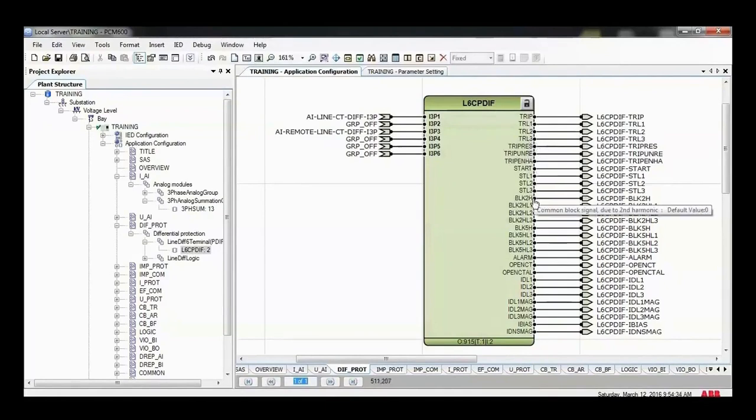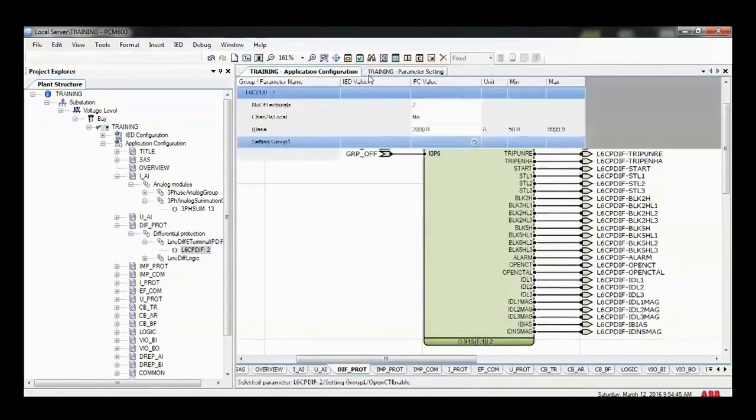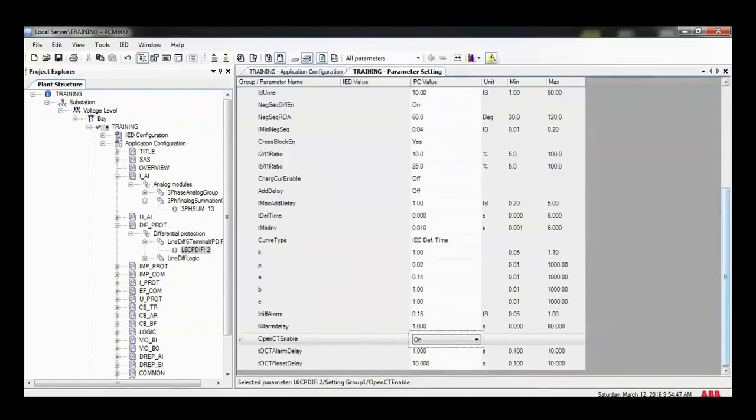The open-phase alarm triggers instantly or after a delay, activating 1 second after detecting an open phase. The setting activates the differential alarm, and the open phase triggers instantaneously, and the open-phase alarm is the one that triggers after the time delay from the setting here. It triggers 1 second after it detects an open phase, all right?